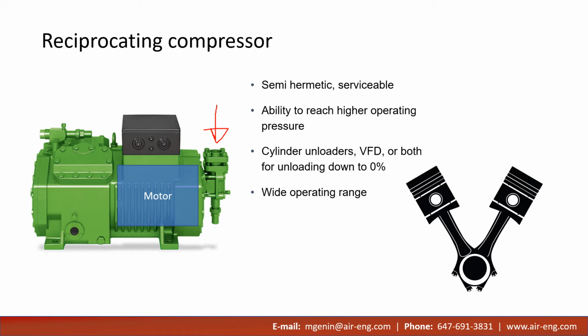and this is why we refer to them as a hermetic compressor, because the motor is hermetically sealed within the compressor and it is cooled by the suction gas. Now this compressor we refer to as a semi-hermetic compressor because, as you can see on the body, there are nuts and bolts. We can remove this body, we can remove the motor and service everything. So we refer to it as a semi-hermetic compressor.